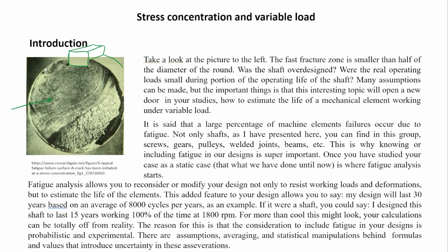For example, on this surface, you might have mounted a coupling, and that coupling might be mounted on top of the shaft, and then you are using this key as an extra guarantee that the coupling, if it's moving in this direction, the shaft is not going to slide inside of that coupling. I hope that picture is a little bit clear. But the purpose of a key is to guarantee that there's not going to be any relative movement between those two parts that are going to be mounted one on top of the other.